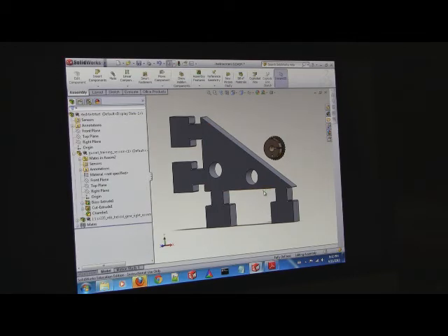So everyone now should have a gear assembly and a gusset in a new assembly, and go ahead and save that. Just insert component. So an assembly also becomes a component. Yes. An assembly can have either parts or sub-assemblies within it. It's like Russian nesting dolls. It's an assembly within an assembly within an assembly, which is perfectly fine. I think I've gone like 10 levels deep at some point. Let me know when everybody's got a gear in there.